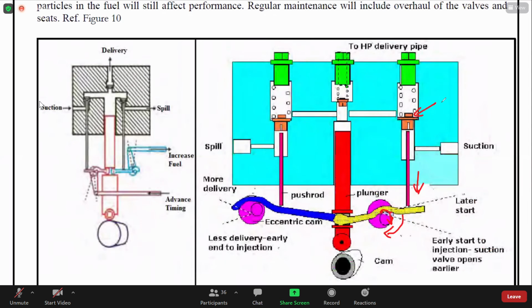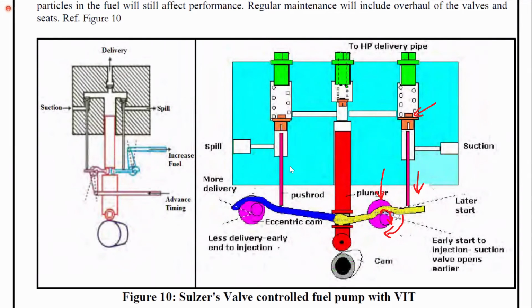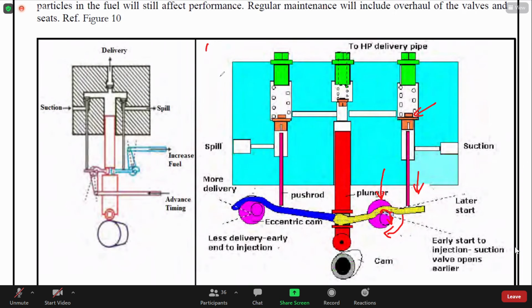Yes, but sir, please understand that this control is a dynamic process. While the engine is running, there will be a control system which, according to the engine load, will be altering the position of this shaft, turning it clockwise or anti-clockwise, right? And trying to achieve the VIT and trying to increase the Pmax and hence the mean effective pressure and hence improve the specific fuel oil consumption. Is that clear? Yes, sir.